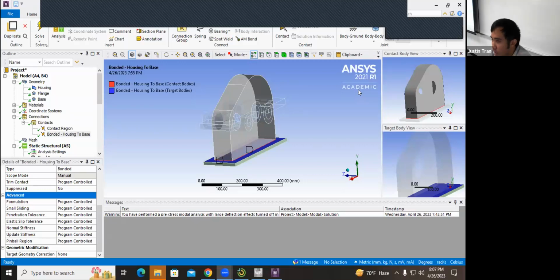For the response surface optimization, you're asking a different question. You're asking it to do more of a wide search. Not only are you trying to find the most optimal solution, you're trying to map out all the different changes. So if you have 3 parameters, you're looking at all the relationships. If you change this parameter and this parameter, then you can expect your outputs to go up and down like this. It lets you better explore the design space rather than just giving you a single answer. It's a lot more expensive, but sometimes you need that for more complicated cases.